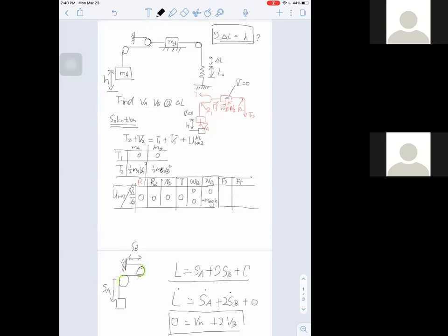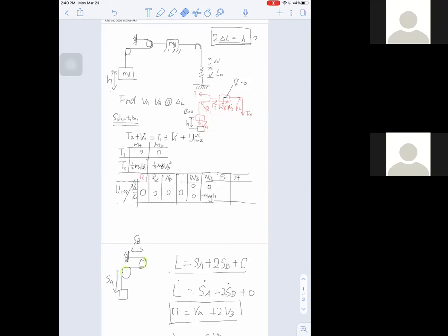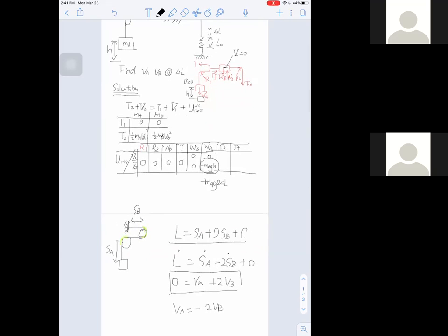And if we know that, we're able to change this term here to negative MA g, replacing H with 2 delta L. So that's the potential energy at position 2 from the weight force. Okay, any questions on that? That's kind of the tricky part. When you have pulleys and ropes, don't just assume the displacements are equal. You need to analyze to make sure you have the correct relationship between the two blocks.